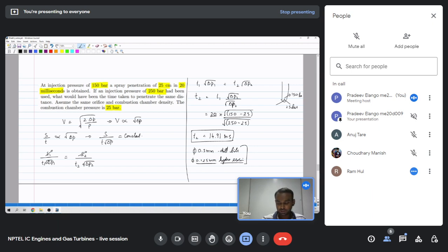In such problems, if you are asked to find the flow rate or the area of the orifice, then you should have an indication of the flow rate. Here we deal with only the velocity and the delta P. For this, V equal to square root of 2 delta P by rho is sufficient. But if you want the area, then we will have m dot as rho A V, right? Now we know